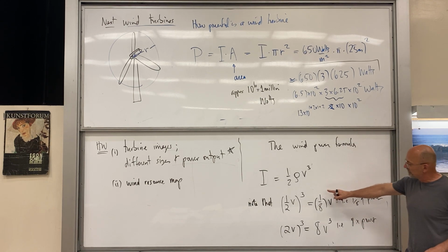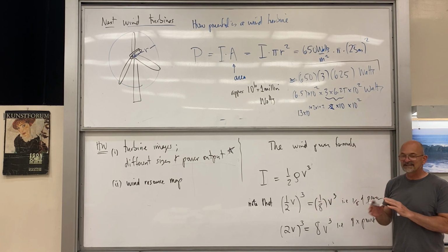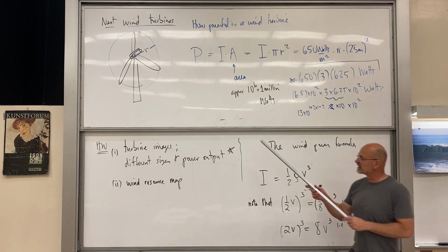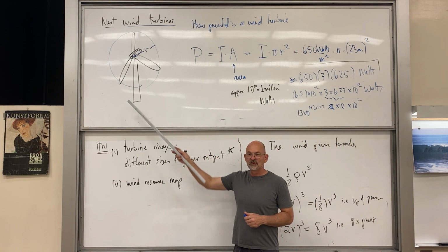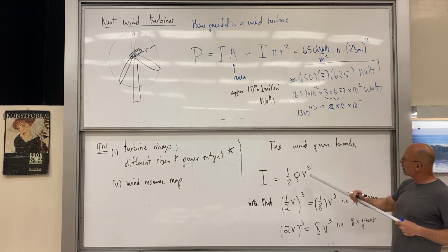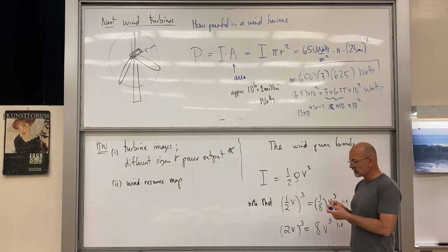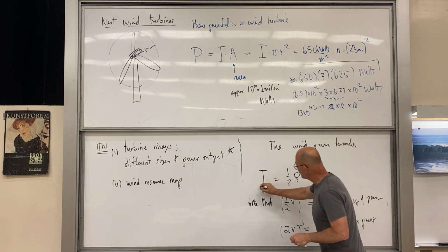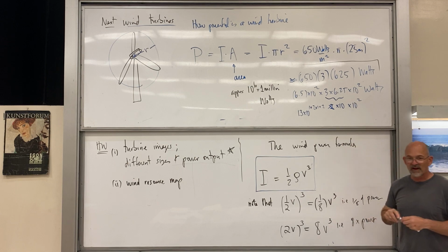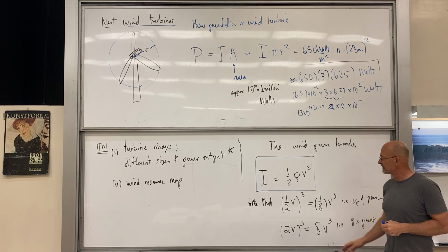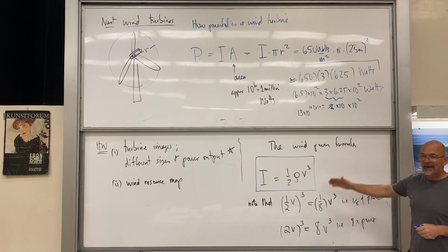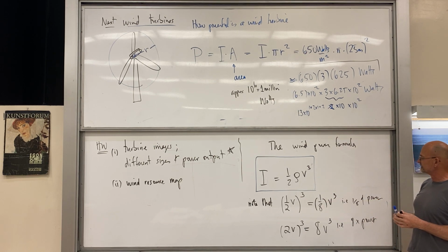So this example tells us that there's a real sensitivity to the wind speed, and it's not just giving you a constant, steady stream of energy the way you might like. Okay. So that's why we actually have to know this formula here, because if we know this, we see why it's sensitive to wind speed. It's not because the wind just dies down completely. It's because even small fluctuations in the wind speed affect the power enormously.